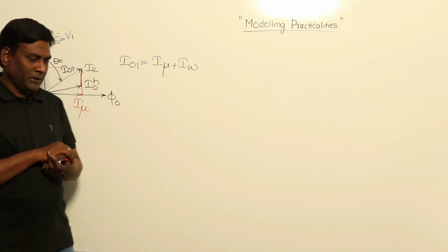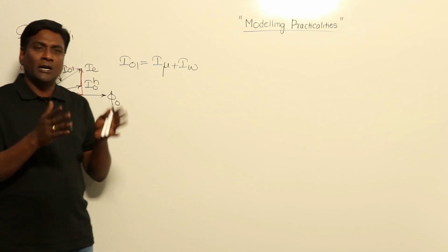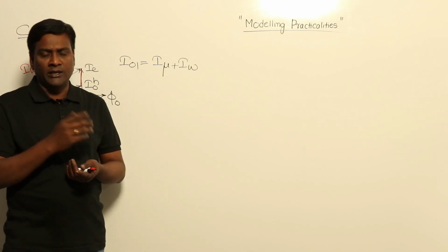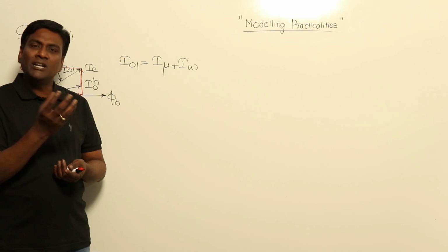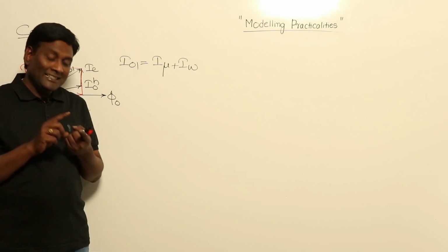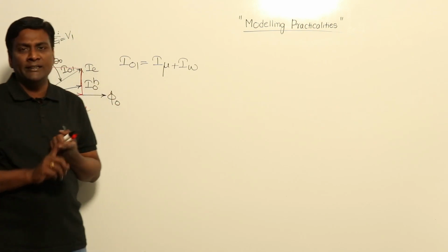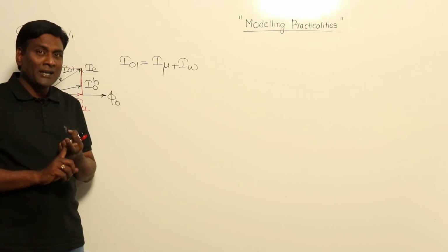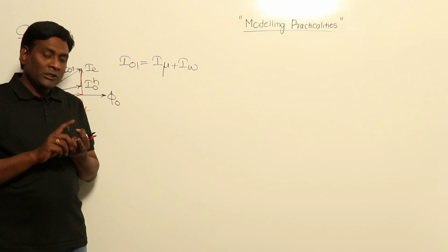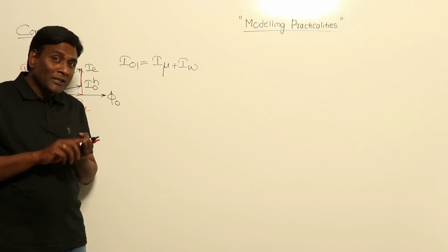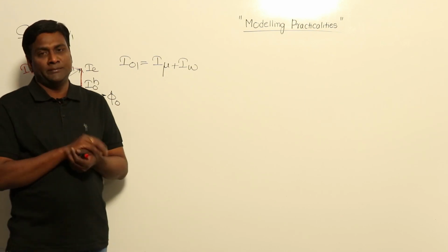For example, think of a wood or air core transformer or air core inductor. Air is an electrical insulator, so the electrical property of eddy currents will not be there. And air is non-magnetic material, so the magnetic property of hysteresis loss will not be there.